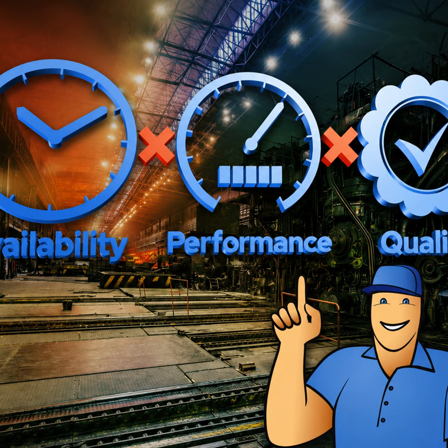Under availability, the main losses are equipment failure and setup and adjustment time. Under performance, the main losses are idling and minor stops and reduced operating speed. And finally, under quality, the main losses are process defects, such as scrap and repairs, and reduced yield, which usually happens between startup and stable production. The reason for mapping these losses is simple. You need to know where to put your efforts into improvements and whether they will make a big enough impact on your OEE.